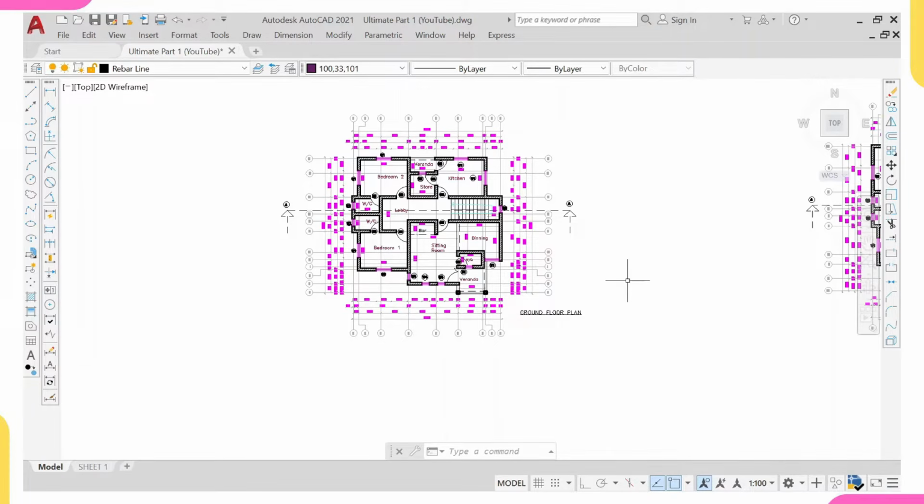So we'll study the architectural building. Is it a residential building or is it a commercial building? Even if it's a residential building, you still study your architectural plan, because in a residential building where we'll be having a gym area at story 1, you know that the loading of that gym area slab will not be the same as other slabs. So these are the reasons why we do study our architectural plan.